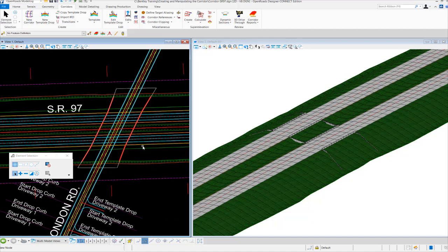So what I want to do is clip out this portion of the corridor so that we can better see my bridges and my abutment walls here. So let's go up to the corridor clipping tool and add that shape there that I've drawn. This is my clipping reference. This is just my bridge shape. We're just going to clip out our corridor inside this shape.